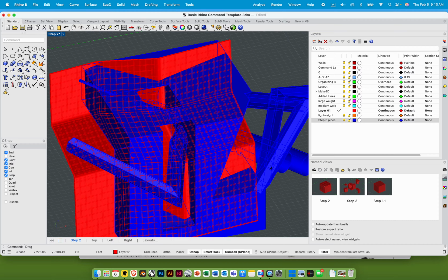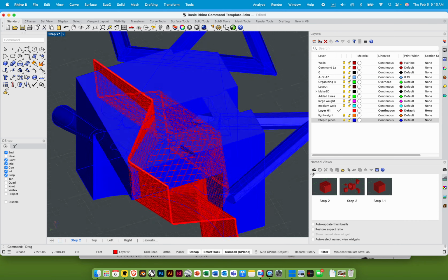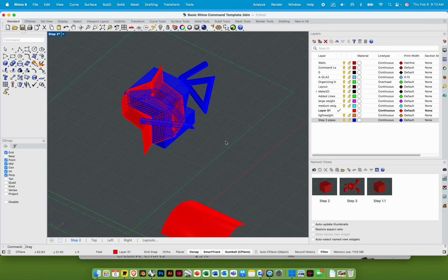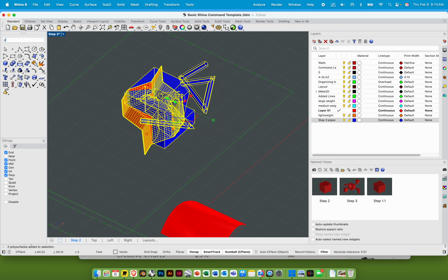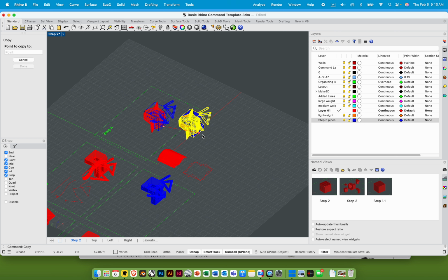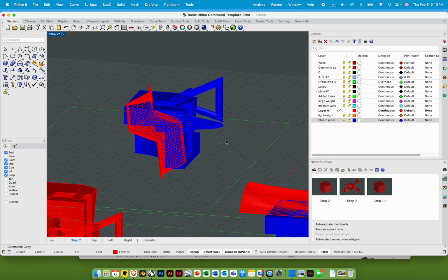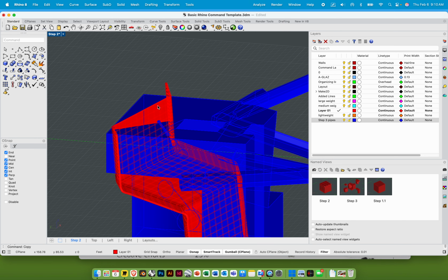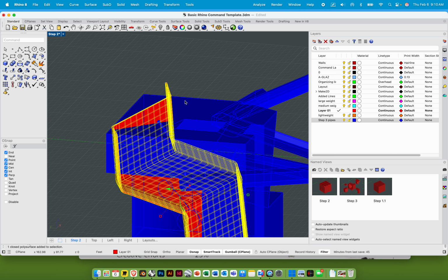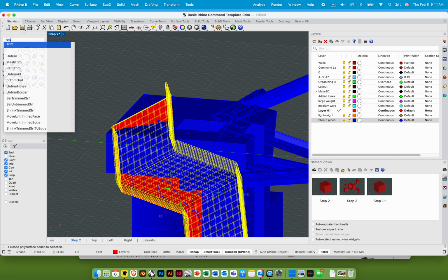Sweet. But at least from what I can tell, for the most part, it seems to be exiting on all four pieces. And let's go ahead and Boolean difference. So I may want to copy that again, just in case so I don't lose it. I mean, what's the harm? You're never going to harm yourself with too many copies. So let's go ahead and try and Boolean difference it. So we'll take that piece. Well, there's two things you can actually do. Trim also works on three-dimensional objects. And of course, we still have Boolean split. So let's try both. In my case, I'm going to try trim first, T-R-I-M.